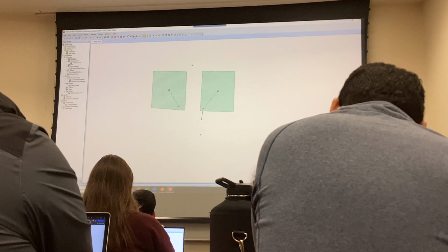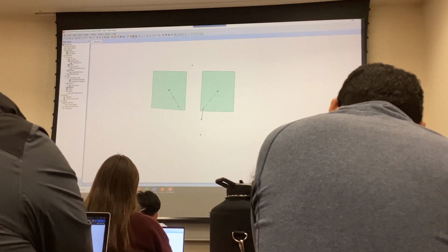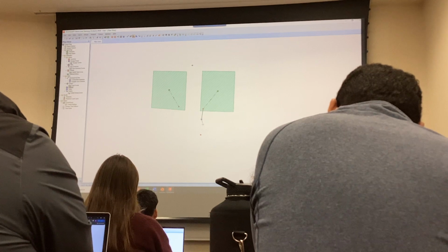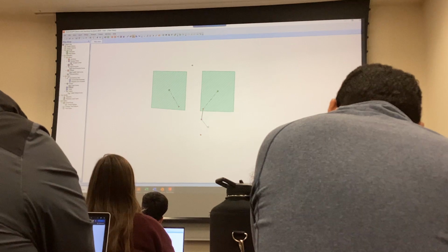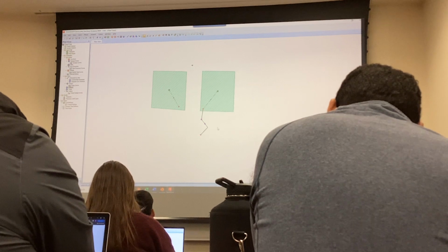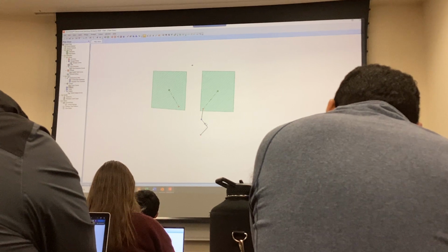So I can click on orifice and say that I already have a design that I have on paper, and I want to follow that. So from my detention basin, I'm going to go through this orifice, which I click on an empty spot, and then it's going to release the flow into this junction. Okay? So now you have this orifice that comes out that's linked to your detention basin.